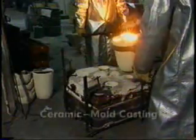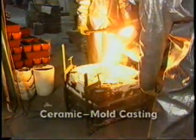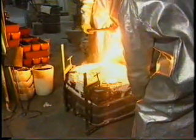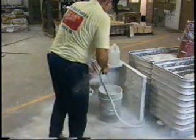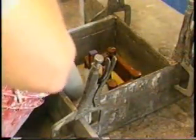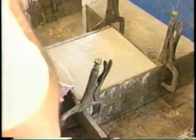Ceramic mold casting is also a precision process, and it is suitable for casting a wide range of ferrous and non-ferrous metals. The mold mixture, in slurry form, includes stable ceramic powders, binders, and gelling agents. It is poured over a pattern and sets in a few minutes to a strong, smooth, and rubbery gel.